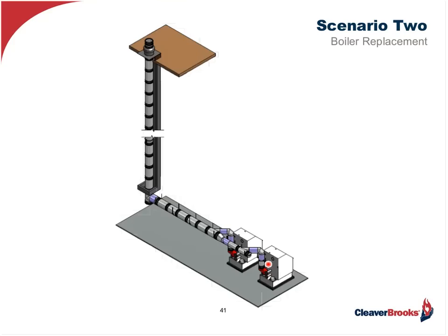These are heating boilers firing natural gas with a low return water temperature, resulting in a lower stack temperature of approximately 200 degrees Fahrenheit. As shown in a previous slide by Steve, a common misperception is to size the breeching diameter the same size as the boiler exhaust gas outlet for the entire run from both boilers to the chimney. We're going to take a look at a draft calculation using that single size diameter breeching.